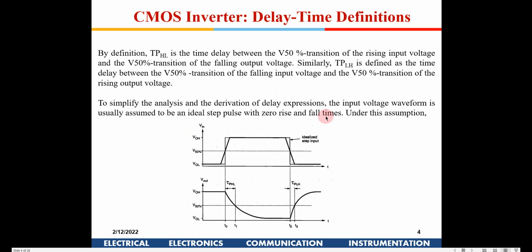Okay, does MOS capacitance have a variation with respect to process? Yes, it will, especially when we design a circuit that actually needs to be fabricated. Then the manufacturer provides, for each MOSFET, for NMOS, an NMOS slow, NMOS normal, and NMOS fast.